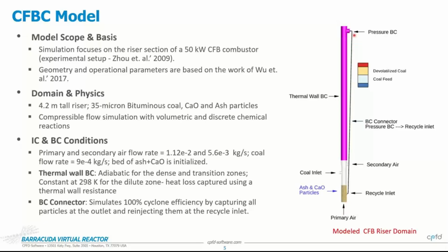So this is not a CAD model. This is just a numerical implementation. That's what the solid backline is implementing. It's visually telling me that all the solids which are going to exit out of the riser section will be brought back by the solver and injected back into the recycle inlet down here. And all of this is done without physically setting up a CAD or gridding it. And so you'll see that for several of these reactors, this is a pretty typical boundary condition that is used, and it's quite robust in nature.